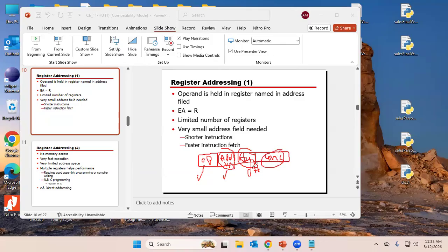What do you think of this instruction? It is possible. I didn't see it in any other computer, guys. But this is the ultimate that can go in there. Well, no, I could even have 2 addresses, 2 registers and a constant. But we said before, don't build an instruction set with too many parameters in it. Operand 1, operand 2, operand 3. One is a memory address, one is a register number, and this is a constant.